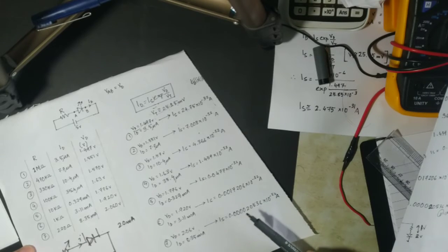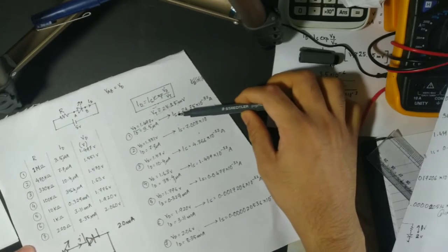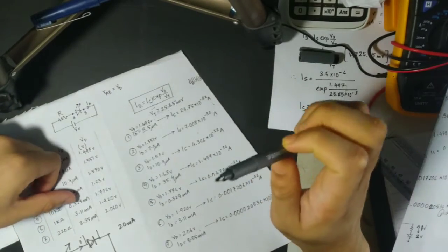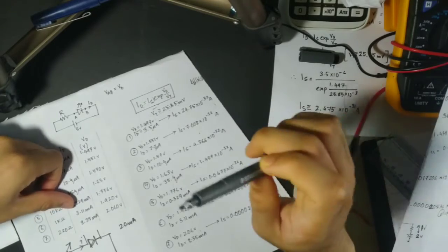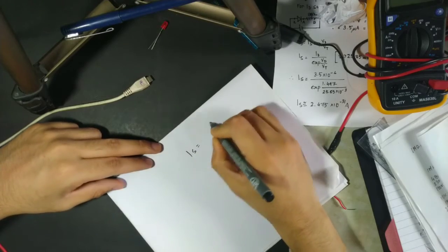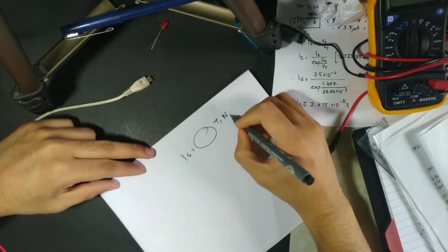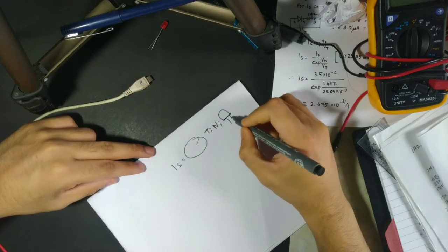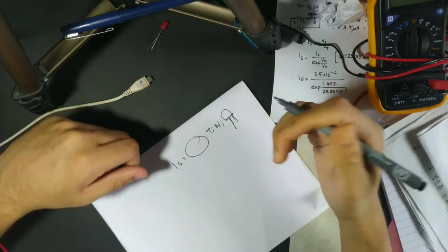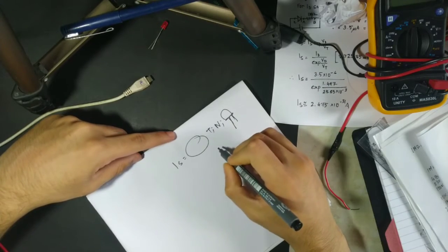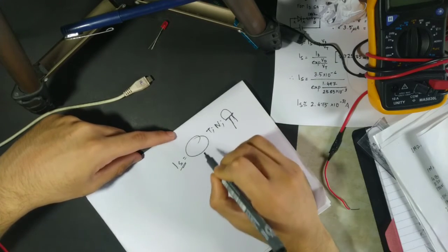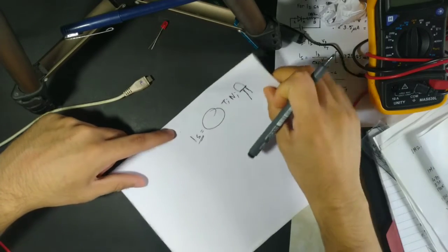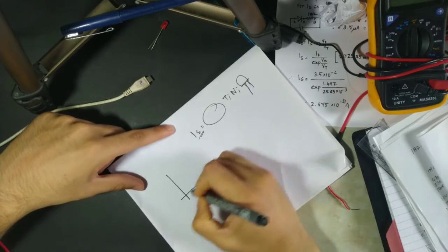It's like completely 0. So we cannot depend on this equation, because there is one quantity which is not constant and it depends on something else. Now what does it depend on? So the IS depends on a lot of factors, like temperature, the doping level of the diode, the structure of the diode, the geometry. It depends on a lot of factors. So it becomes very complex for us to carry out the equation where a value which is dependent on so many factors is there. So what we need to find out is a simple model. For that, the simple model is using the graph.